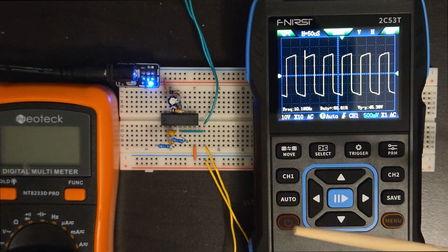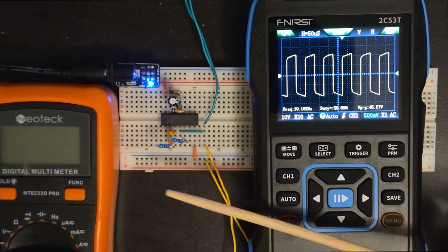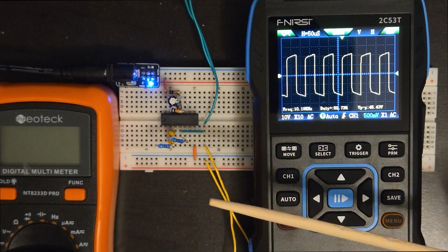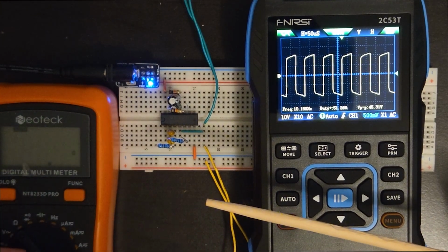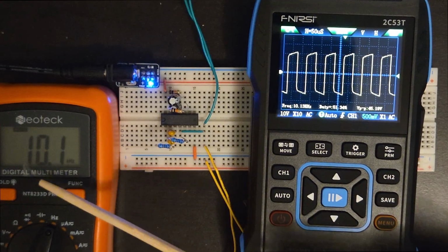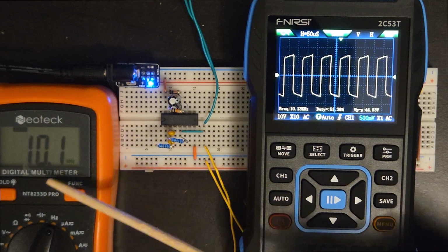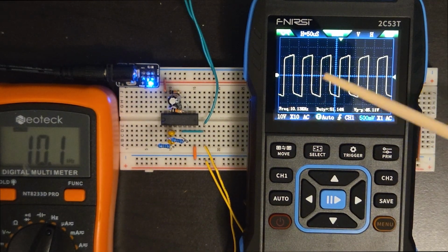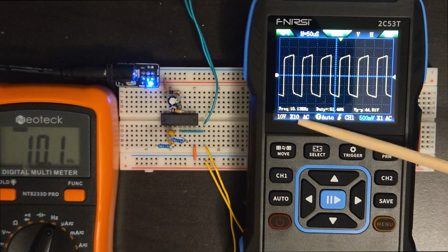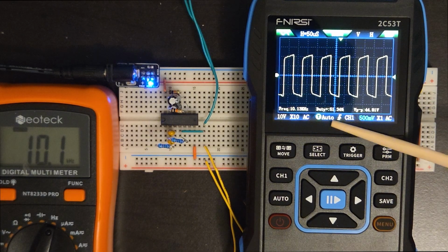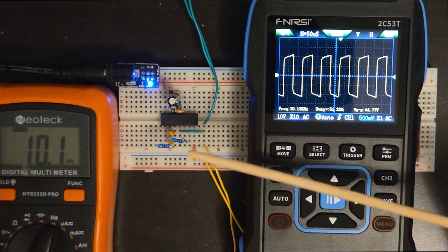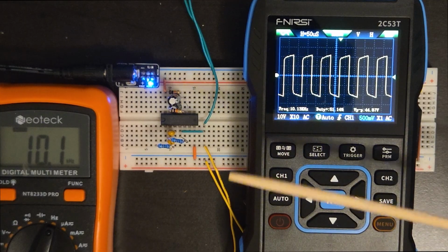So there are a couple ways to confirm the claim that this is a 10 kilohertz frequency and 100 microsecond period. The first way would be with these digital meters. First we can see on the DMM, we have 10.1 kilohertz, which is roughly 10 kilohertz. And as well on this oscilloscope, we see a couple more things. First of all, a frequency of 10.13 kilohertz and a duty cycle of 51%. Some of these measurements are going to be slightly off just due to resistor and capacitor variance in their values.